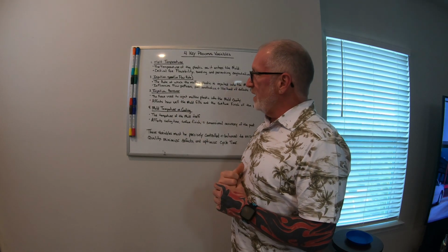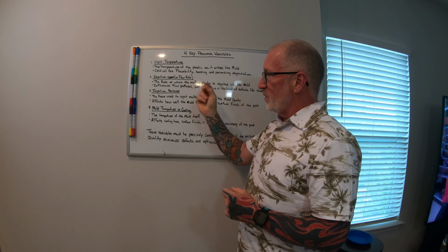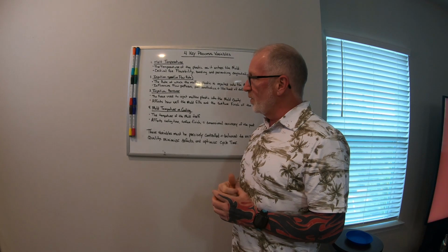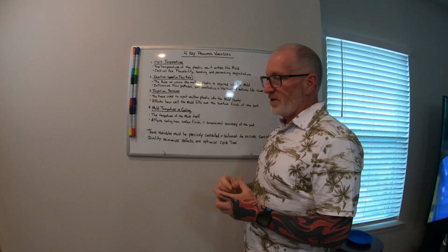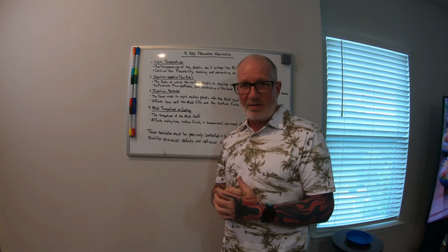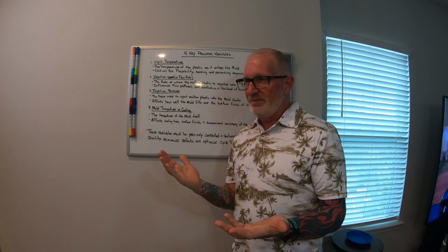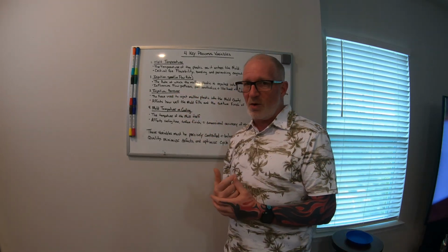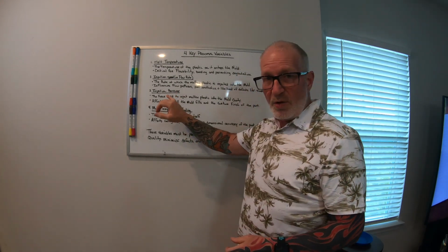The next one would be injection pressure. So after I get the fill rate where I want it to be, to where the part is about 95 to 98% full, now I'm going to go with the pressure. You're going to take whatever pressure this is here, and let's say it takes 1500 psi to fill that part, okay? You're going to cut that in half, okay? So it'd be what, 750? So you think about 750, so maybe I'd start off at maybe 500 psi and work my way up, because the lower the pressure, the better.